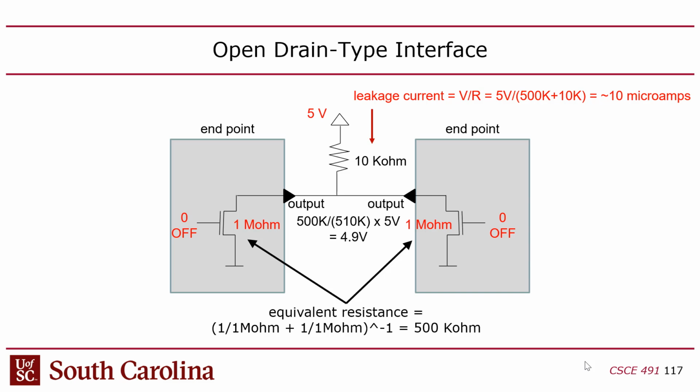still unclear, right, Alex? It looks like it's on the IMU itself. Yeah, oh, that's right. Our latest information is that this pull-up resistor is located on the IMU, the sensor. Not on the ESP32, and it's not on the board because we didn't put it on the board. The reason why we think it's in the IMU is that if you pull the IMU out, I2C doesn't work at all. So yeah, we think that pull-up resistor is on the IMU. It's on the sensor, right? So there's this pull-up resistor, and that makes the signal a 1.